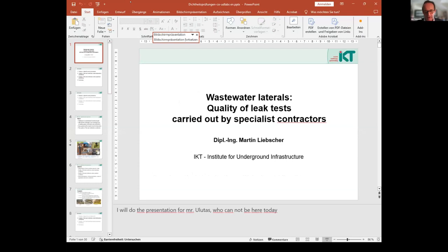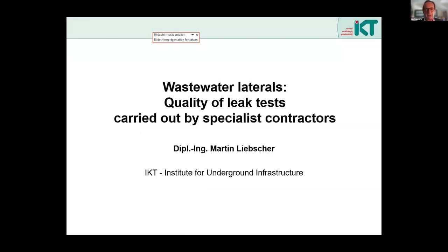What we're about to hear about is perhaps another one of the basic standard techniques, which is a leak tightness test, looking to see whether there is a potential for infiltration or exfiltration. It can be used on brand new pipes, it can be used on existing pipes, or it can be used after there's been a rehabilitation of a pipe in order to see if what has been created is leak tight.